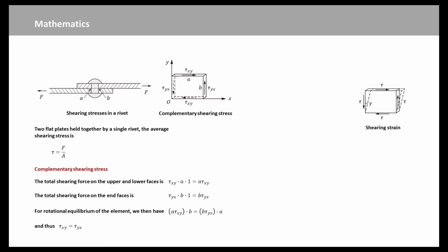Shear stress in a material gives rise to shear strains. Consider a rectangular block of material again, subject to shear stress tau in one plane. The shear stresses distort the rectangular face of the block into a parallelogram. If the right angles at the corners of the face change by amount gamma, then gamma is the shear strain. The angle gamma is measured in radians and is dimensionless.